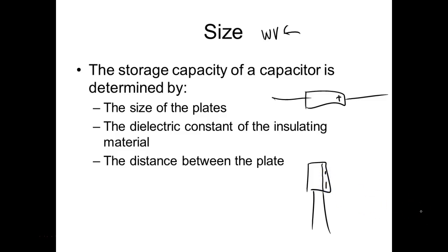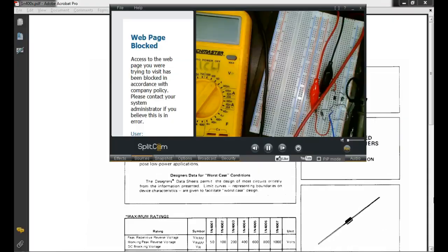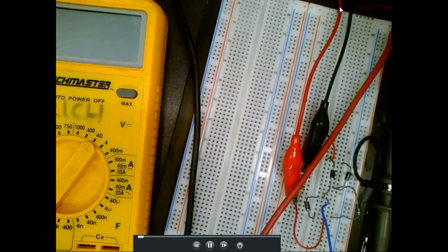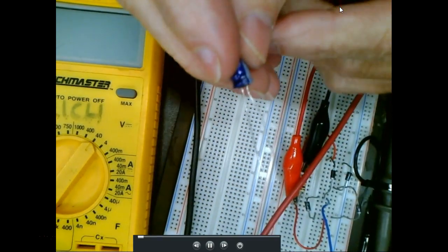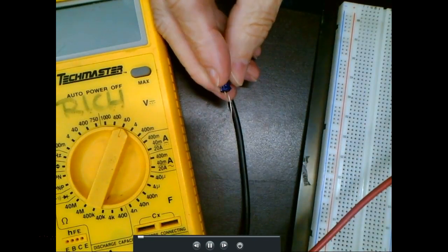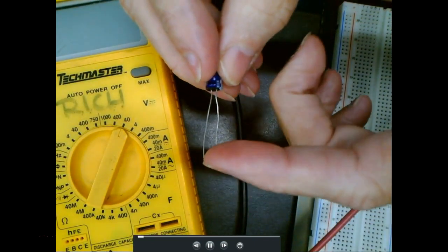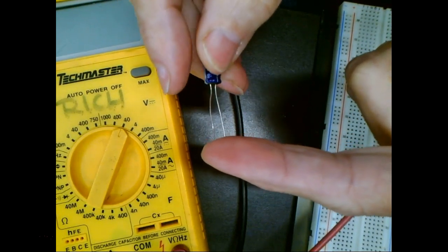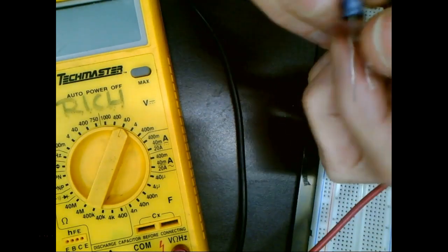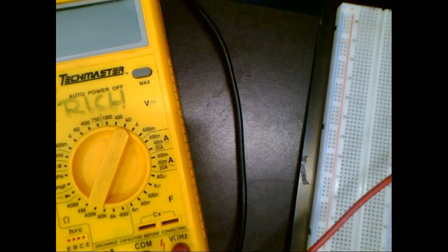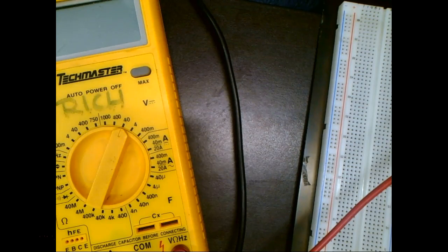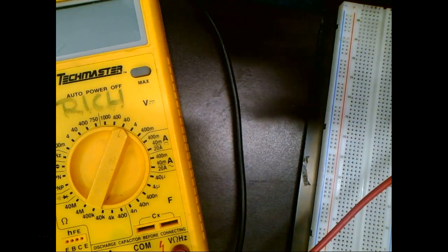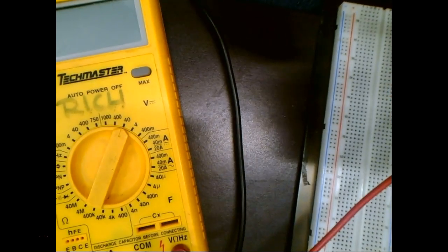They also do something different, but it disappears as soon as you cut the leads to put it in a circuit board. When we're holding this thing, another thing they do is make one lead shorter. Let me put it against black. You'll see this lead over here is shorter. And what lead is that? That's the negative lead. That's also true on a lot of radial lead diodes. It's also true on radial lead LEDs. A lot of your LEDs are radial lead LEDs. If you ever look, the cathode is going to be the short one.